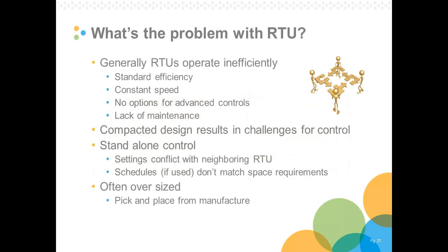The standalone control of rooftop units does affect their efficiency also. There's a lot of conflicting neighboring RTUs that don't have appropriate set points. Generally, it is one thermostat to one RTU, and the thermostats are not coordinated perfectly. And a lot of times that's what we see.